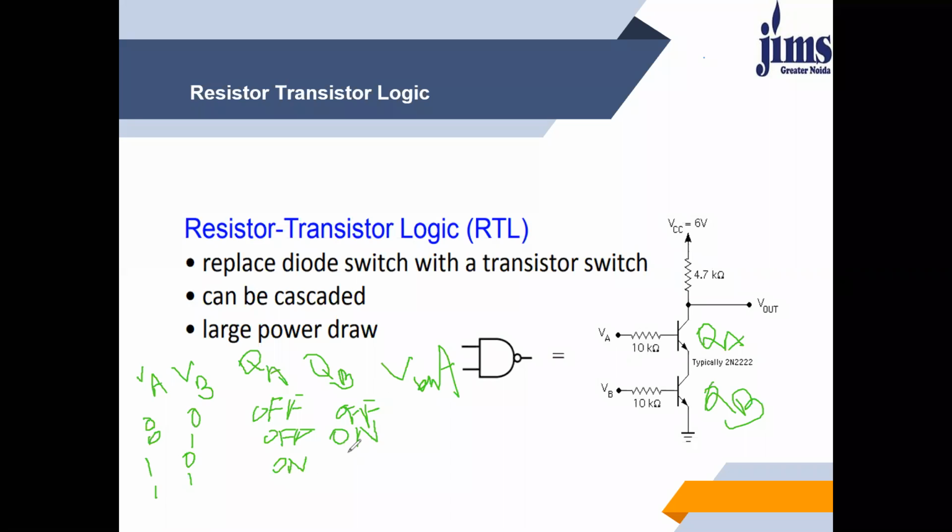So in this, it will get off, and again it is on here. Now, what will happen? Whenever both the transistors are off, then the current will not find any path and will go to output 1. When the second condition comes, QA is off, so the path will not be found by this 5 volt. Then again the current will flow to output.